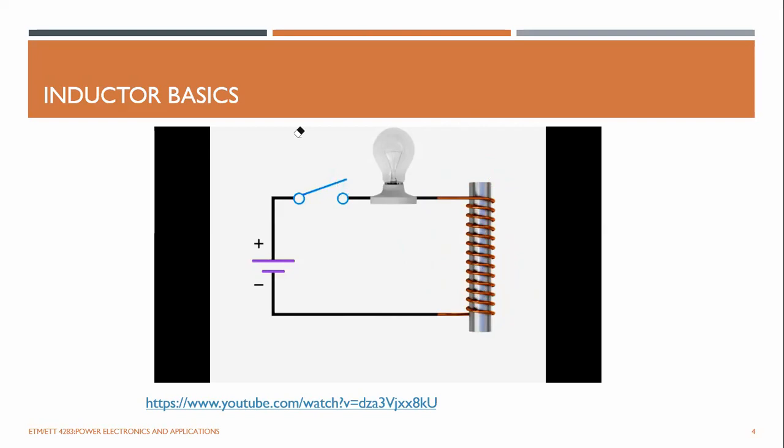The other interesting thing is, in a capacitor charging circuit, the capacitor voltage starts from 0. But in inductor circuits, when you switch this on, the light bulb is off. This means the battery voltage VB goes directly across the inductor, because the inductor has the highest impedance initially since it doesn't have any flux. So it gradually creates this flux, and this VB goes down.